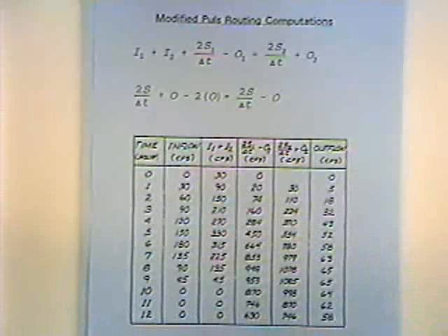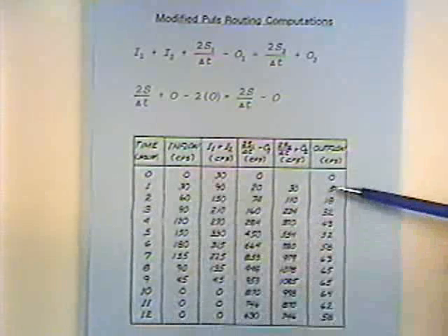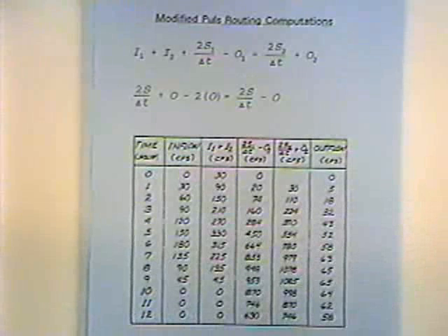And so, given the inflow hydrograph, we've computed the corresponding outflow hydrograph, where all of the site characteristics, the topography of the detention basin site or reservoir site, plus the outlet structure characteristics are incorporated in that storage indication curve.